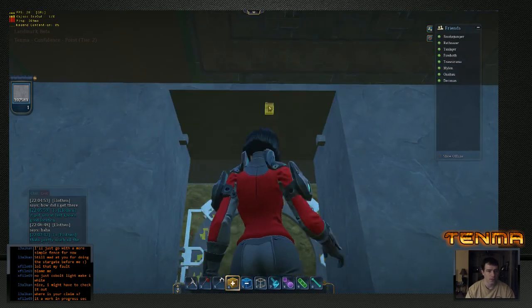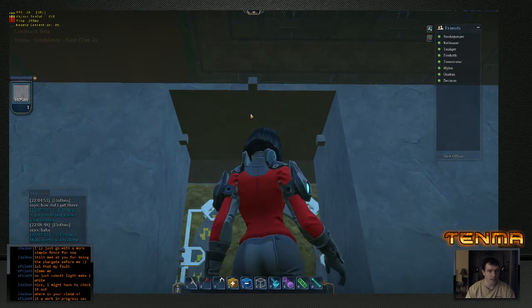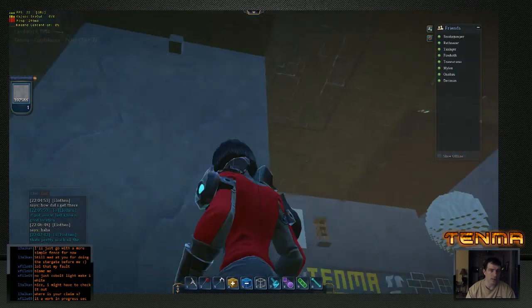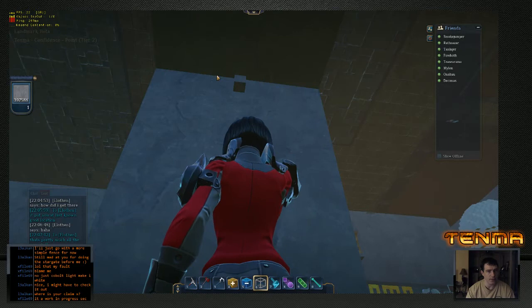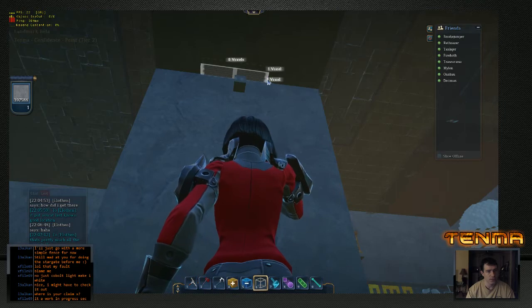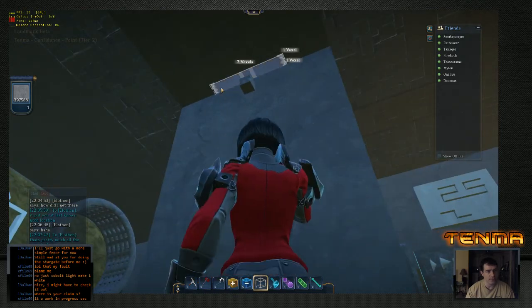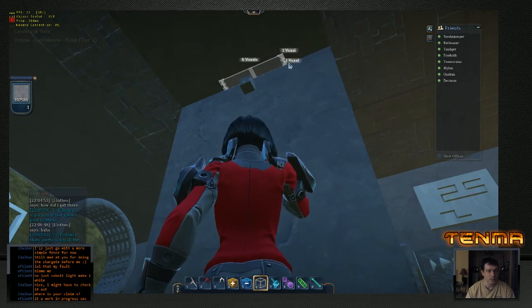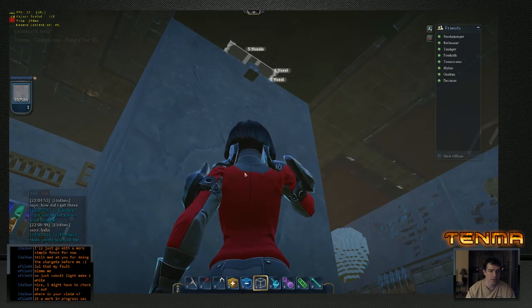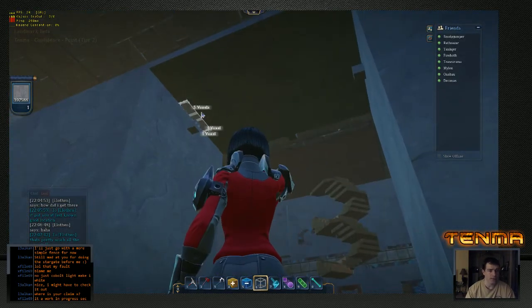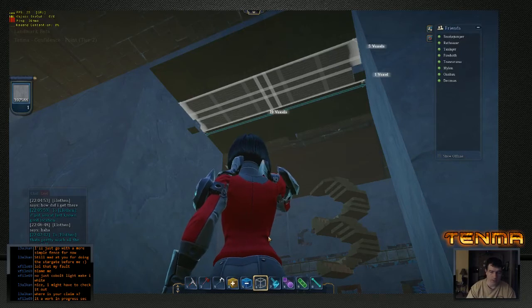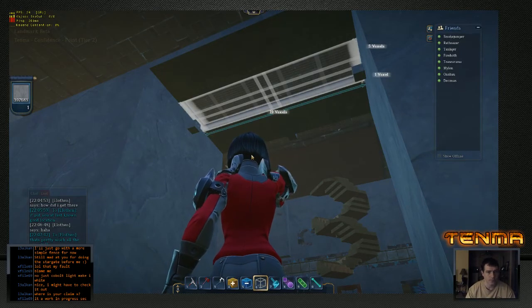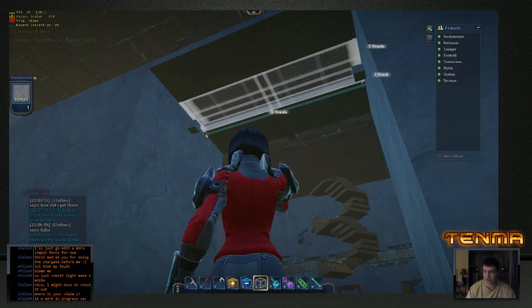Okay, and then I'm going to put one right there so I know my center point this way. The next thing I'm going to do is make a selection right here, and I want it to be 5 voxels. Pull this in just a little bit, and we're going to pull this thing across, and I'm going to delete that whole section out. So it's 5 voxels. My gate itself is going to be 3 voxels wide because I want a gap pretty much all the way around this thing.